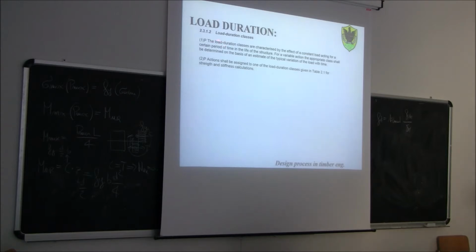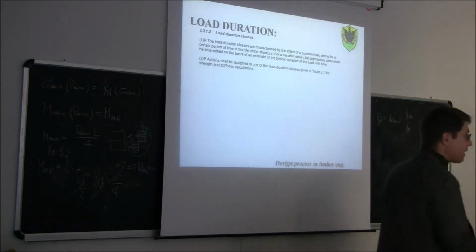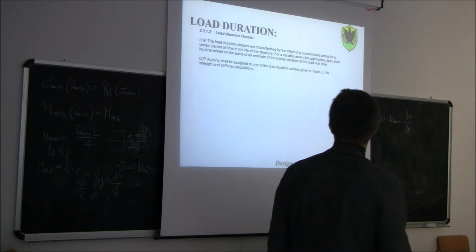If you read the Eurocode 5, the load duration classes are characterized by the effect of a constant load acting for a certain period of time in the life of the structure. So for a variable action, the appropriate class shall be determined on the basis of an estimate of the typical variation of the load with time.